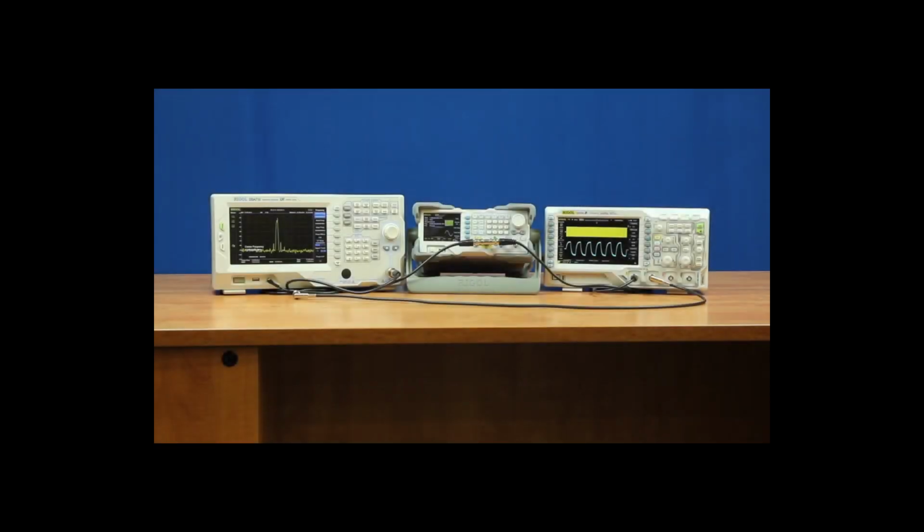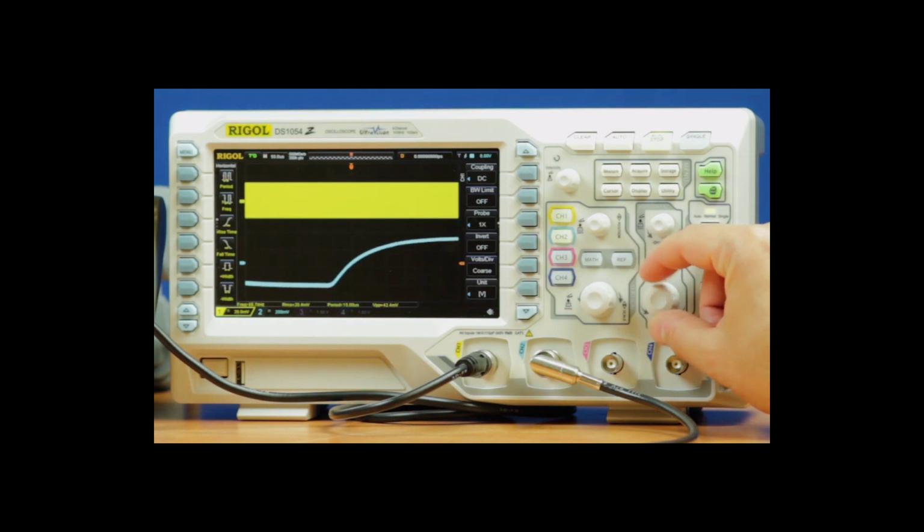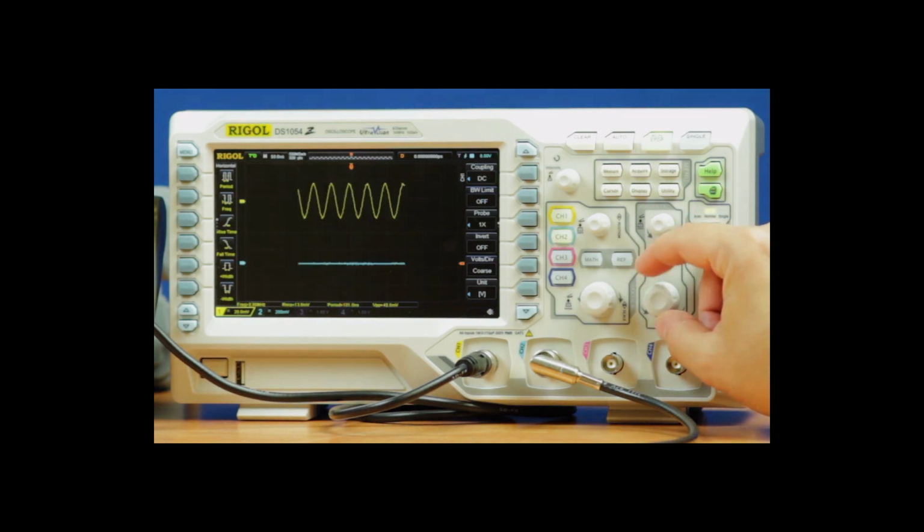Here's our second example of digital data transmission and demodulation. Here we're looking at an FSK. So we've loaded the FSK settings for all three instruments as a frequency shift key. So the signal is moving between two frequencies. In this case, like with most frequency modulations, we're moving between two frequencies that are relatively close together. That's causing a couple things. First of all, on the scope, we can clearly see the demodulated bits coming from, in the blue, the spectrum analyzer. We can also see that the channel 1, the yellow, is very consistent. It's at a much higher frequency.